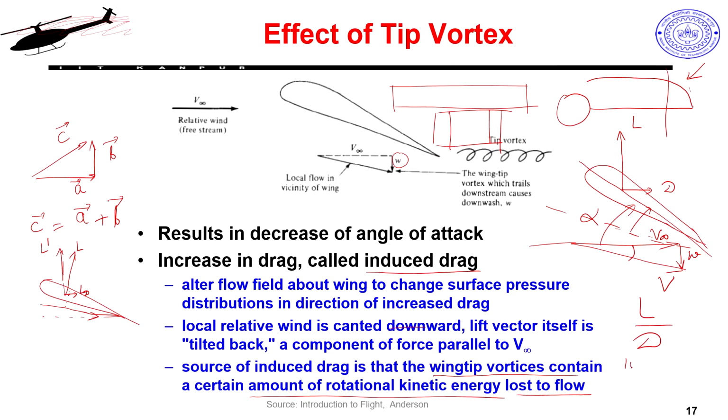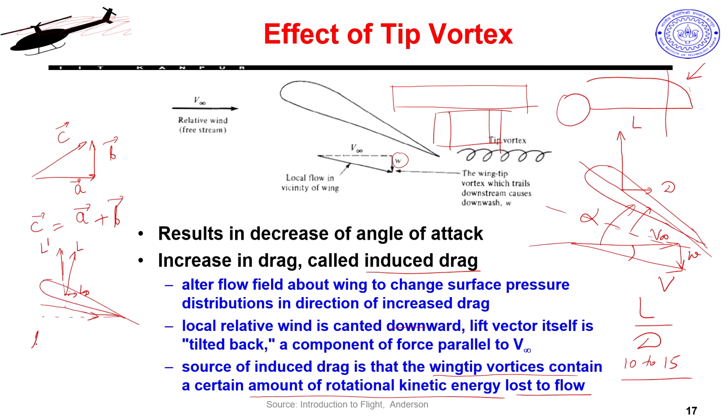So, manned aerial vehicles or full scale aerial vehicles would typically have L by D of the order of 10 to 15. So, my Cessna would be somewhere in between, 12, 13, 14 maybe. And the glider which we have, Sinus Pipistrel glider, actually claims to have L by D of 23. So, you can note down here, glider has claimed L by D of 23.